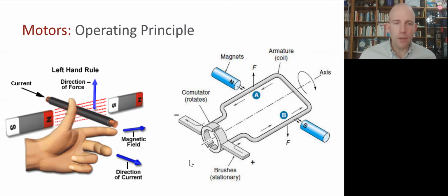Now, to get to rotational speed and torque from this force and linear velocity, we can think about what's happening inside the motor. It's inconvenient to have a very long actuator. You'd like something that's more compact. So to achieve this, people take the wire and make a loop. And actually, in a real motor, there will be lots and lots of loops that form the coil. And this part of the wire is on this side of the axis.